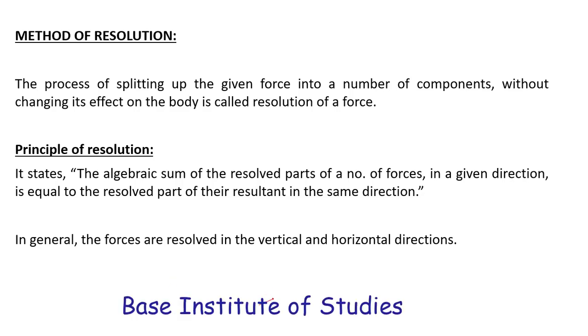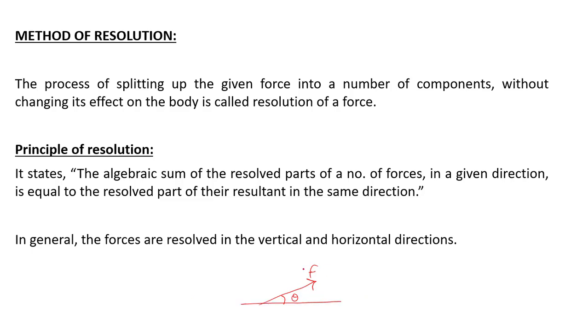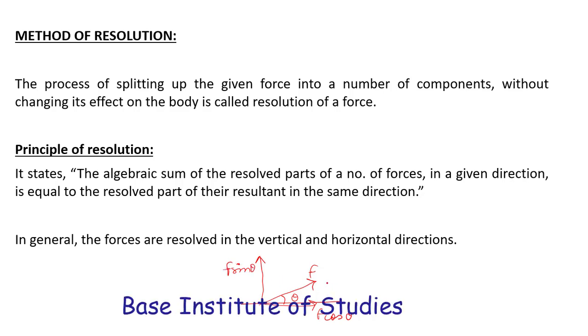Let's take an example that there is a force making an angle theta, acting in this direction. Then this force can be resolved into two components, one vertical and the other horizontal. Let us say this is the horizontal part and this is the vertical part. Then this will be F cos theta and this will be F sin theta. So this is the resolution of this force. We have resolved this force F into two mutually perpendicular components, F cos theta and F sin theta.